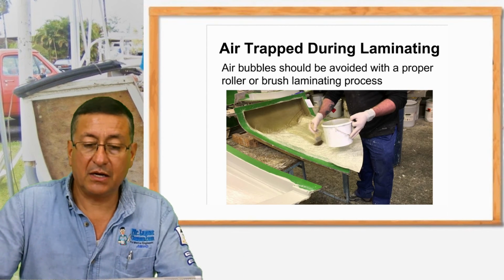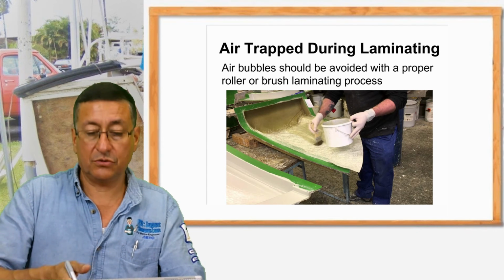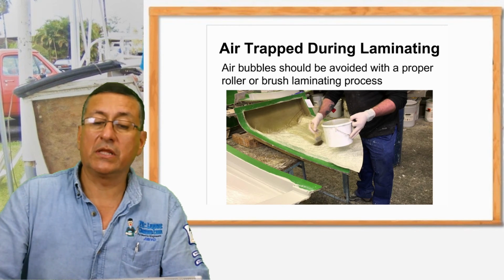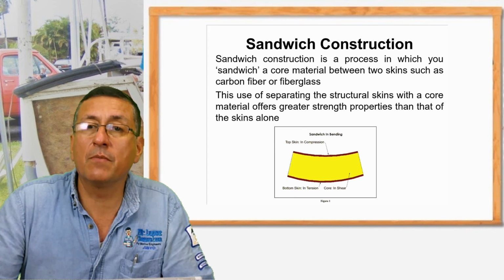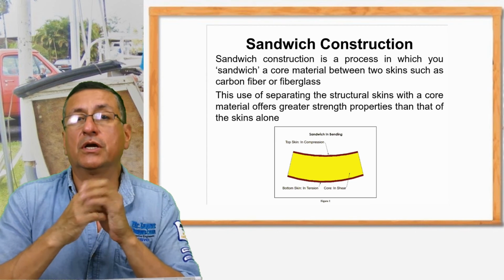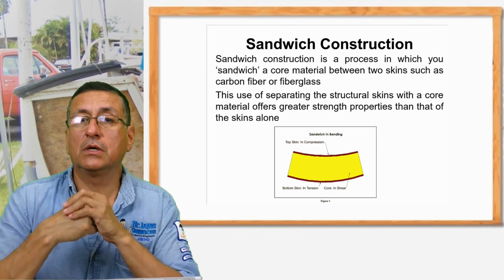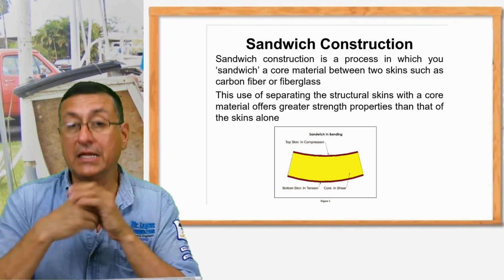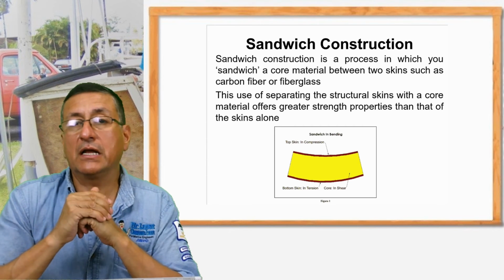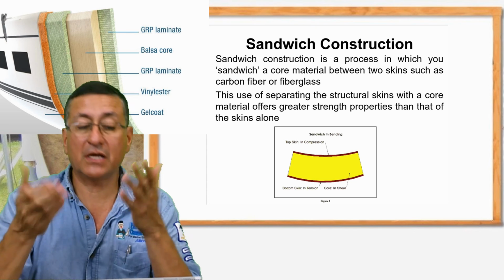At this moment they are creating the mold, used to create ailerons and different parts, laminating the fiberglass with the mold. In the creation of the mold, normally you can use structural foam, balsa, or plywood, and you laminate that core material. You laminate both sides with the fiberglass and resin. It's like a sandwich. The name of that technique is sandwich construction.